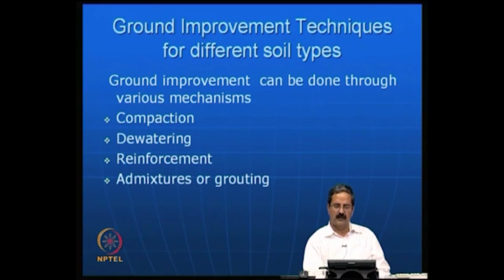So, one can consolidate in a proper manner and get whatever you need. Dewatering is a standard technique people have been using, like removal of water using some dewatering machines or applying some loads, so that the water that is present in the clay structure slowly comes out.